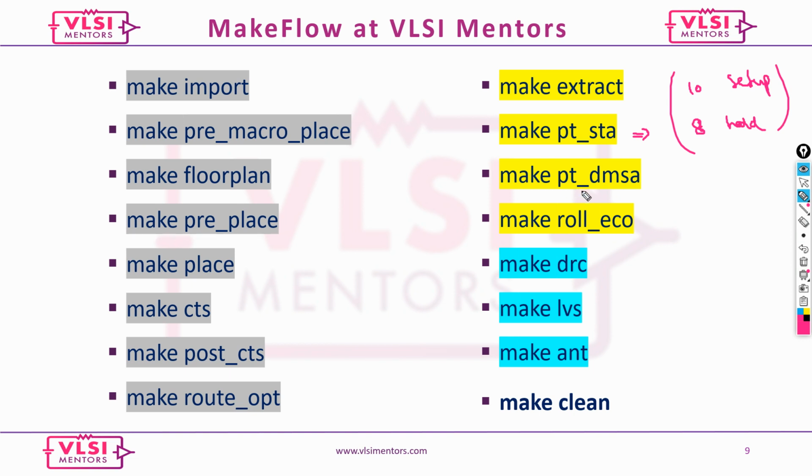Once you are done with this, this is just pure STA. And then you might want to follow the timing closure flow. I'm sure some of you are working in industry, and the majority of people, from the registrations that we have got, are looking to get into industry. The DMSA actually helps in coming up with your timing closure, timing ECOs. So basically you have a physical aware timing ECO generation.